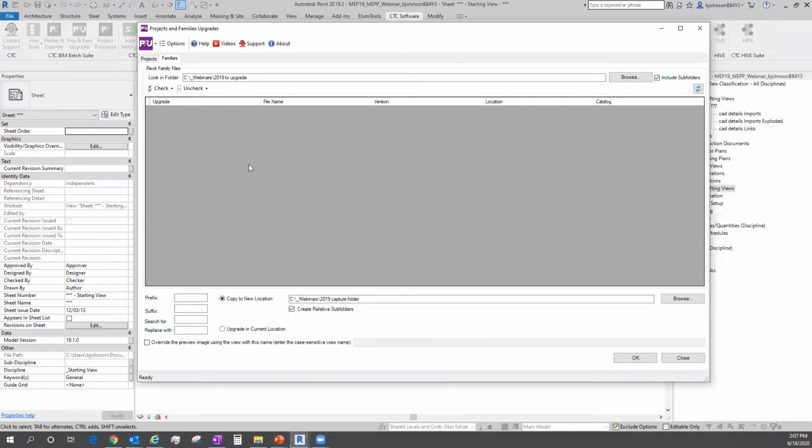And usually with this particular tool, I could upgrade those 4,000 plus families in about 2 days, just doing batches. Usually I'd grab 4 or 5 folders in my library locations and then turn those into a batch, run them, put them in the new finalized location, and then go back and look at the potential errors that might have occurred. Occasionally you'll have a 256 character file name limitation.